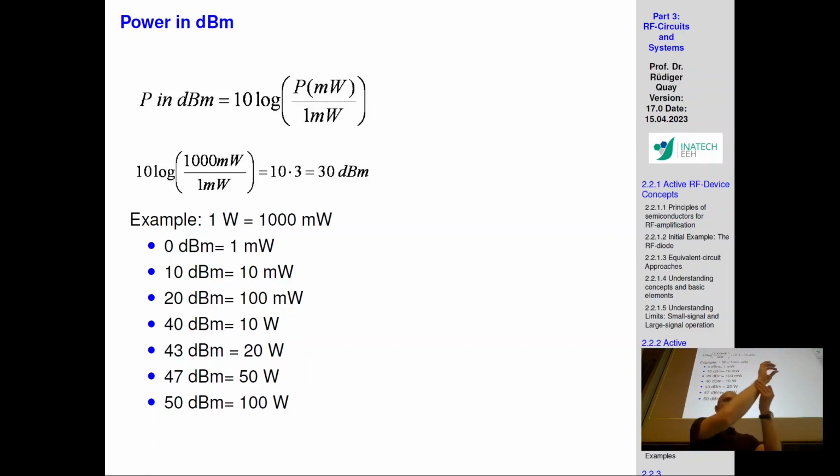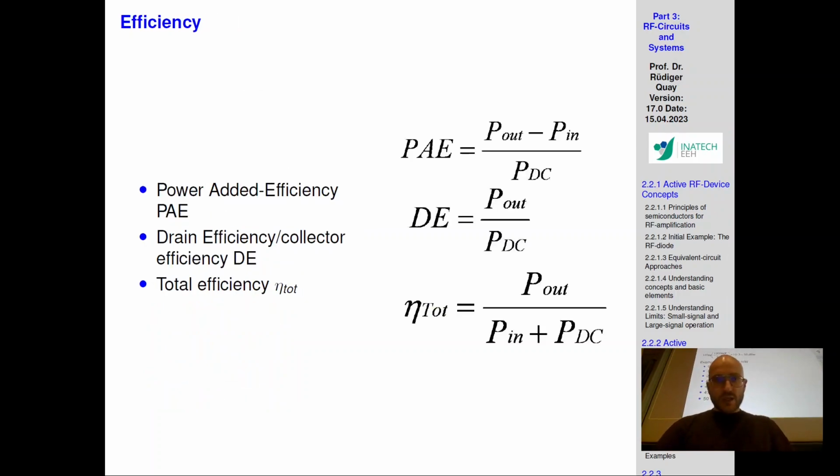When one transistor is a two-port device, another transistor is a two-port device, another transistor is a two-port device, so you have all these two-port devices, and in order to make it easier for you to just add up the gains, not to have multiplication, we talk in dB then. And dB allows you to just add up those.